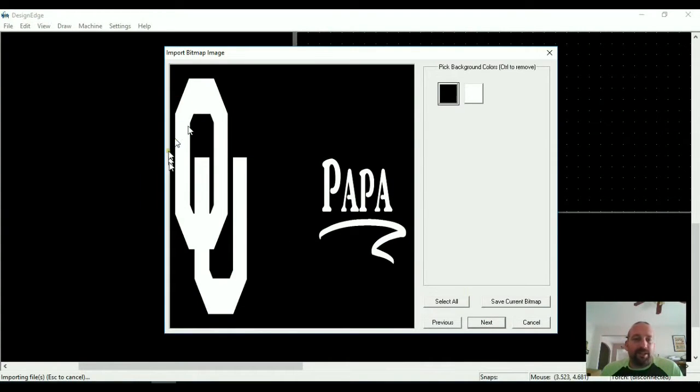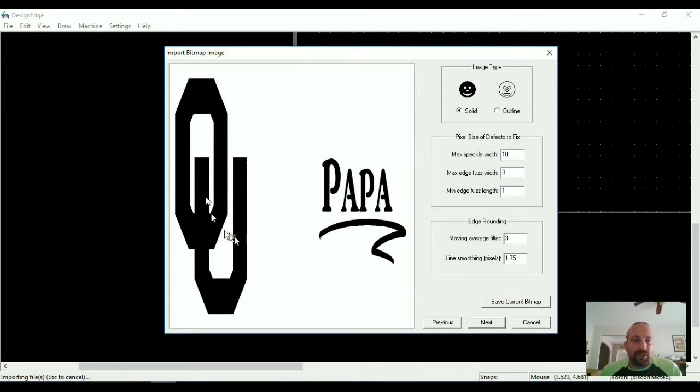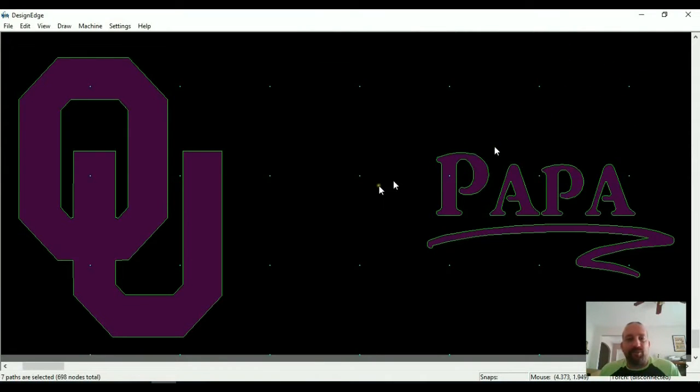So when I tell it to change it to black and white, it's a much easier picture to see. My background color in this case is black, so I'm going to pick black and tell it next, and then it shows me what it's going to look like, never mind the ratio. And I pick here whether it's a solid, this is filled in, or this is an outline drawing. If it was just an open circle and I wanted it to make a filled in circle, I could pick outline and it would fill it in for me. And then click next and it will convert it to vectors for me.